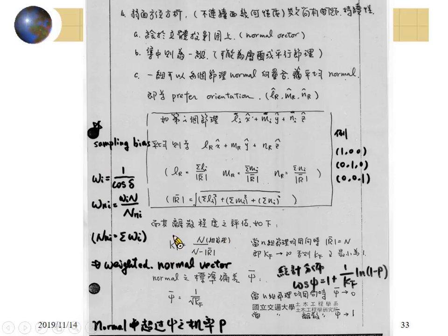And this shows you the variability of the discontinuity you measure, and you can also calculate the standard deviation using this. We call it kappa. Kappa shows the variability of the normal vector relative to the mean value. If you have a larger variability, it means you will have a larger standard deviation, and you will have a very large uncertainty for your engineering design.